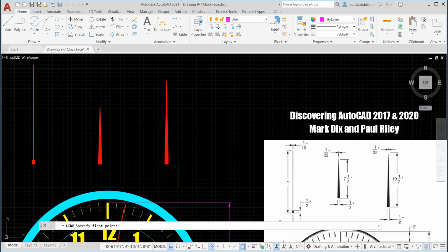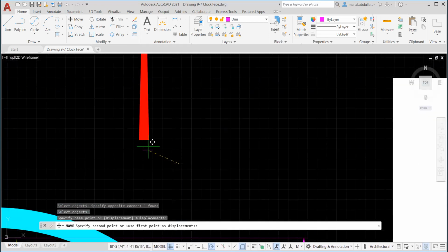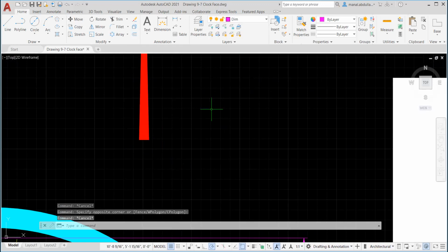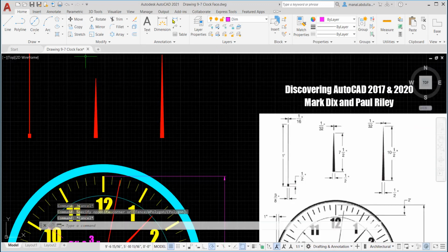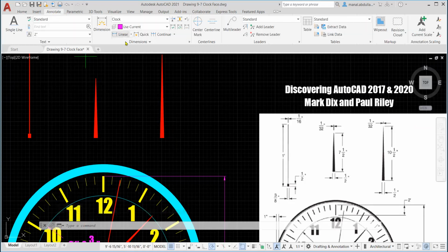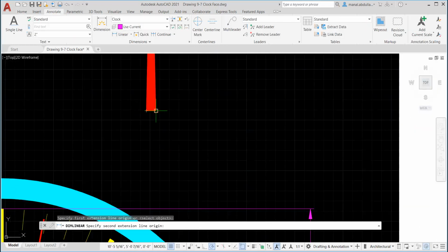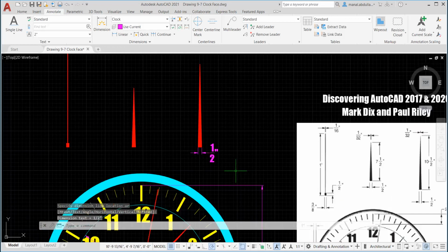Here it is half, so I'm gonna draw half, enter, and I'm gonna move this line from center to center. Okay, also I'm gonna move it to the same layer. Now I can put this dimension, so I go to Annotate Linear, and I can put this dimension as it is half. Okay, let's put the other one here, linear, from the top.